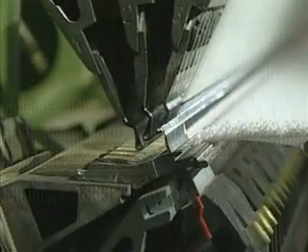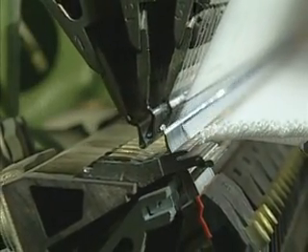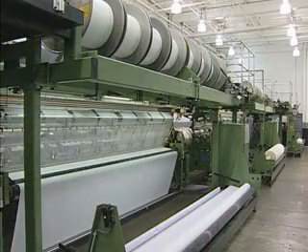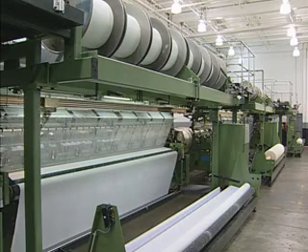If more than one yarn is provided for each needle, more elaborate fabrics can be produced. These individual needles knit simultaneously across the width of the machine. Warp knit fabrics have a flatter, closer, less elastic structure than most weft knits and are most often run-resistant. The most common warp-knitted fabrics are tricot, Raschel, and crochet.